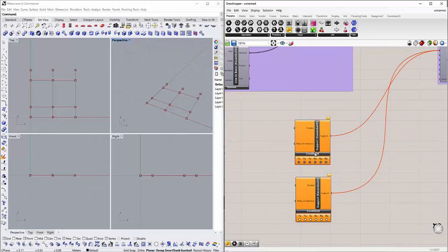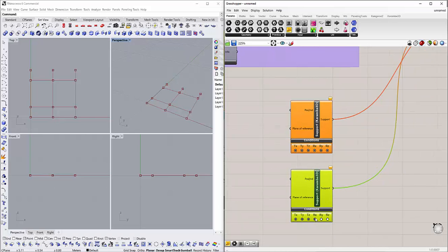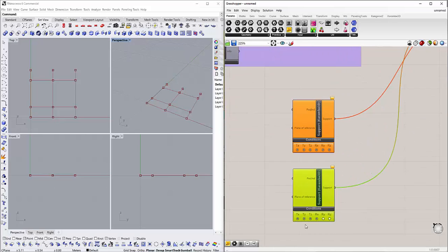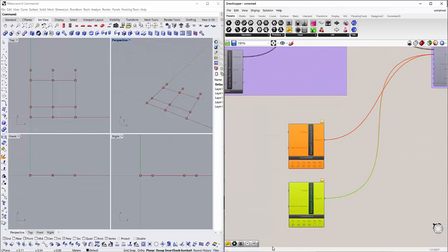As you can see, this is a fixed support, and the next support I want to create here is moving support. And for moving support you only select rotational X and fix it from all directions, and you give degree of freedom in Y and Z direction, so it can rotate in Y and Z direction.